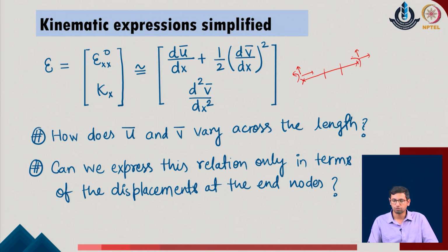So, what we mean to say is that typically when we are trying to solve the problems using the general structural analysis approaches, we identify the displacements at the nodal points. Now, the displacement values which are identified at the nodal points are typically expressed such that at any other intermediate point of the given system also, if we want to define the value of the displacement parameter or the strain parameters, we can express them in terms of the same nodal values of the given system.